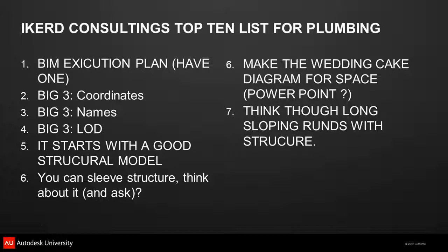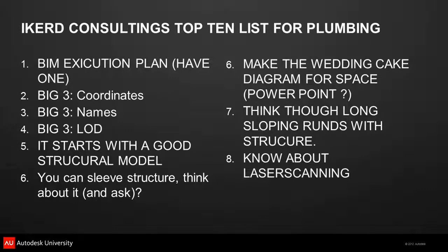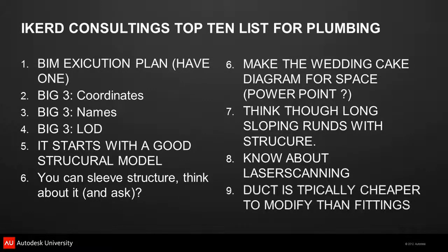I'm going to talk in particular, if you're a designer, you may not have in your scope to fully model manufacturing level of development of your elements throughout your project, but at least think through your long runs and how those will fit in the space. Some things to know about laser scanning that are very germane to plumbing and how it fits with structure. Duct is typically cheaper to modify than fittings, and I'll dig into that as far as plumbing fittings. I'm talking about large bore piping.